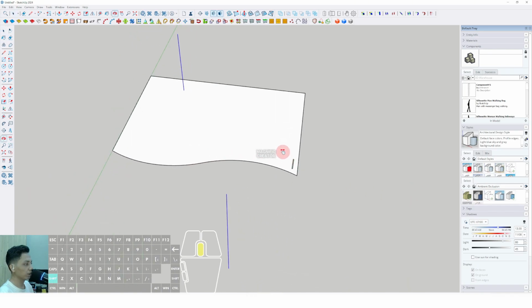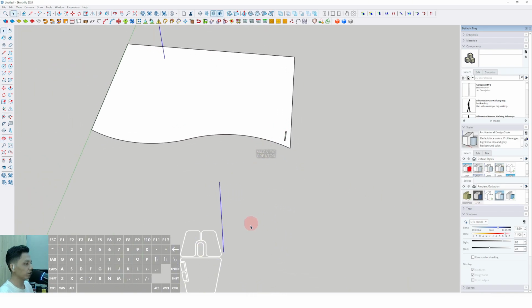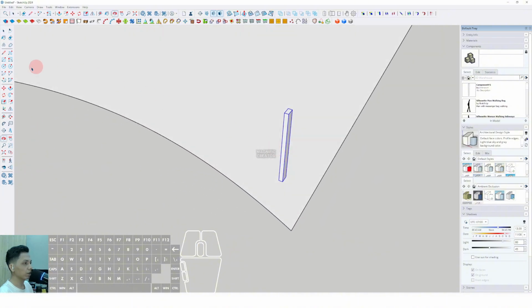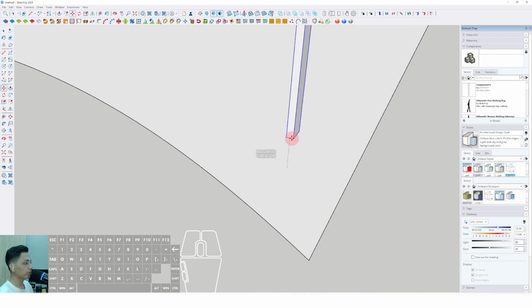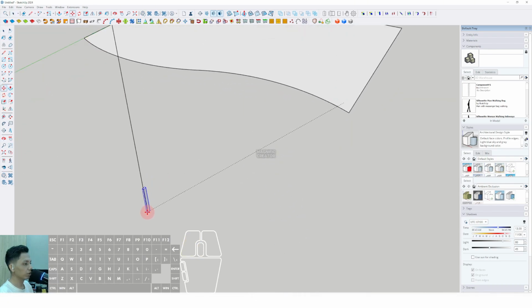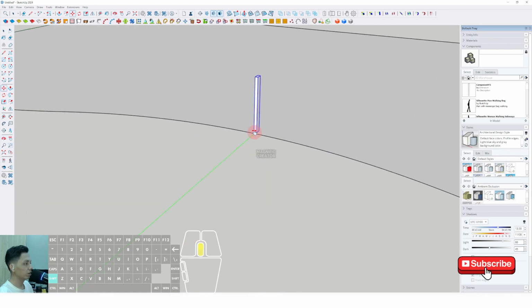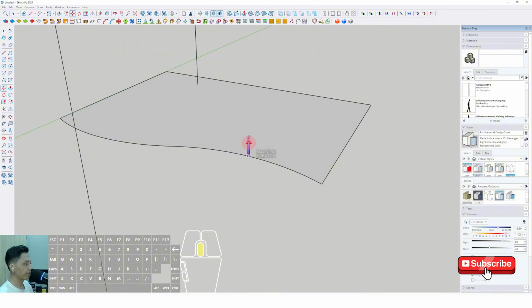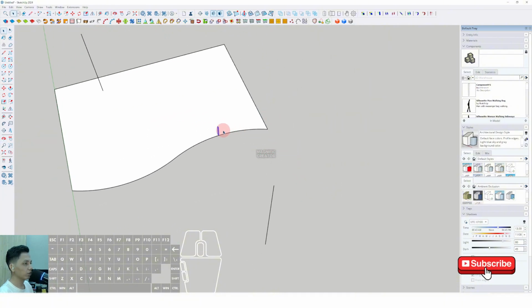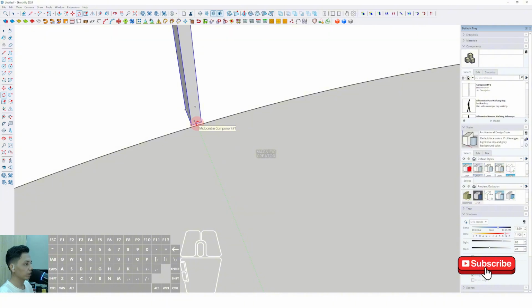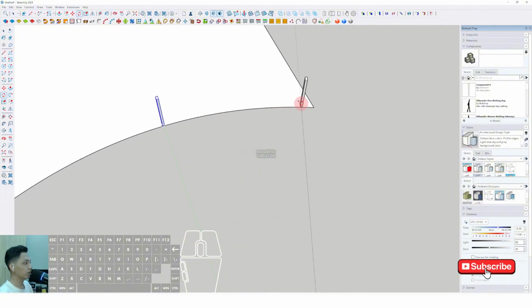Okay, both of the lines are very important to make a guideline. To make the guideline, we have to move and duplicate the vertical frame, and then we can select this vertical frame, select move, and place it to this position. And then we can move it to the front in here. Then we can duplicate this one. We can select rotate and click from this endpoint and press Ctrl, and we can click this midpoint and place it to this position.